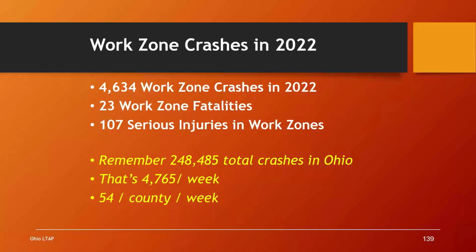If we're on high speed or high volume roads or sight distance restriction areas, make sure we don't just use the standards, use what's listed as guidance and options as well. By enhancing the safety of our work zone, we're going to cut back on the number of these crashes.